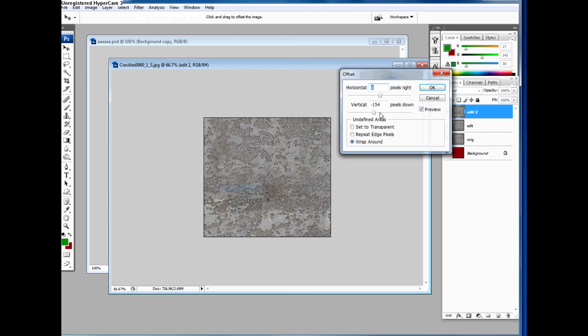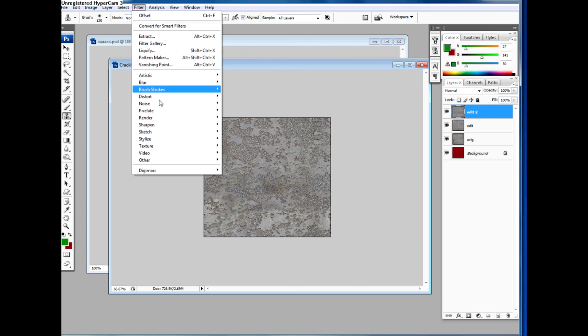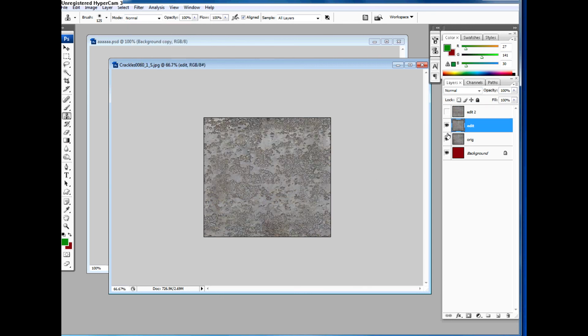So again, you can do the same thing again where you're erasing, or if you want, you can try the clone stamp tool. But again, be careful where this brush is going, because if you're doing this and you're painting down here, you're creating a new seam here. So be careful when you're fixing seams not to paint along the edge, keep your distance. So just to let you know that that's where it was, the offset, and that's a rough explanation of how we will make tileable textures.